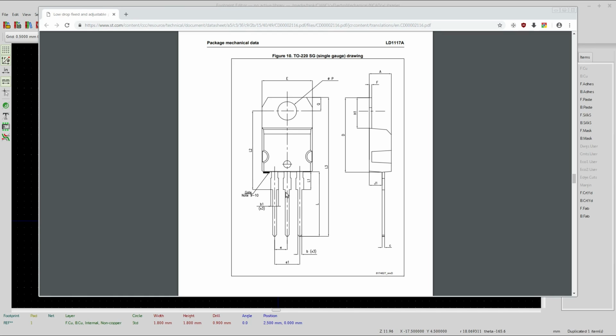So you don't want to solder it in and just press it over, because it's going to want to spring back up. And if you're just going to use some thermal adhesive, that's okay. But I have noticed that if it does get really hot, sometimes the stuff pops back up. Anyways, you don't need to have any kind of preload on it. So bend these things first.